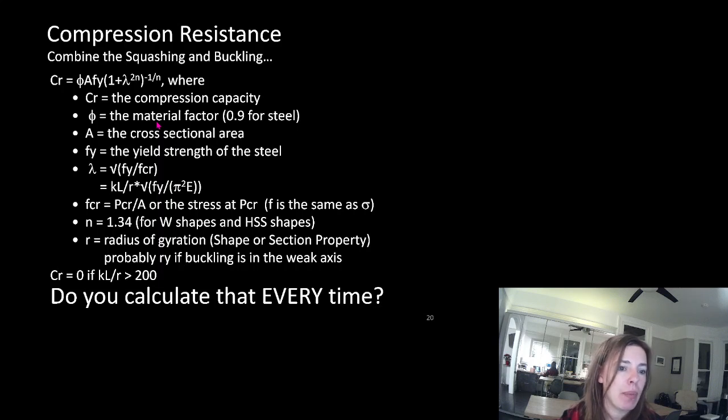For an example, maybe an old building is being renovated and we're putting new things on the roof. Steel that's 350 MPa only became kind of ubiquitous in the industry a few years ago. When I started, plate and angle and channels were often only 300 MPa. That's why some of my examples still show 300 MPa.